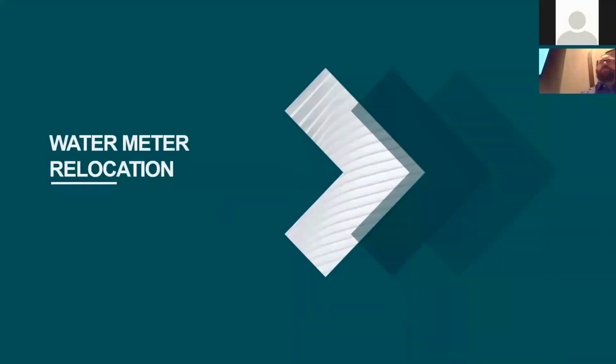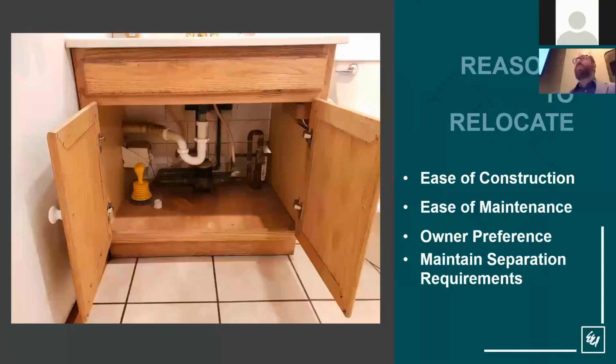Water meter relocation is another topic that's going to be pretty important to have a good idea of what you want to do going into it. Why might you want to relocate a water meter? Well, for one, ease of construction. You also want to consider maintenance in the future. And then owner preference is not a very high priority, but it's also something to consider to make them happy. And then you also may need to relocate a meter to maintain separation requirements from sewers.